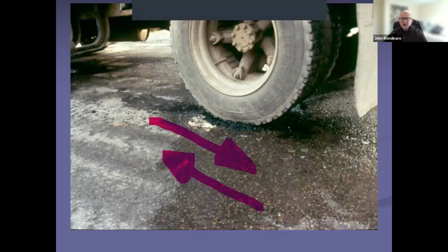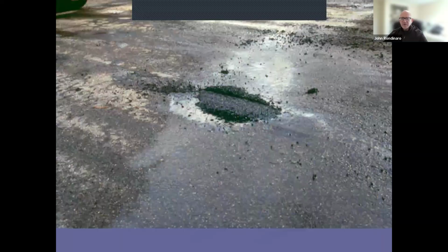And what really makes it work is it's pressure activated. You hit it with that truck tire, so you're backing up over the material and then pulling forward. There's your end result. You've got your pothole patched, and that material is going to stay in that hole. The only thing I would add is I'd run over it one more time to knock down those high edges. But otherwise, you've got a good temporary patch in place that should last you all season.